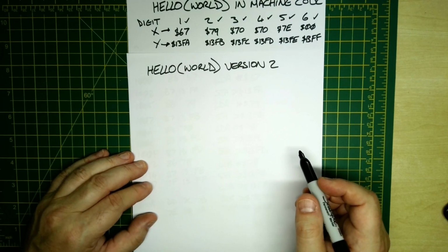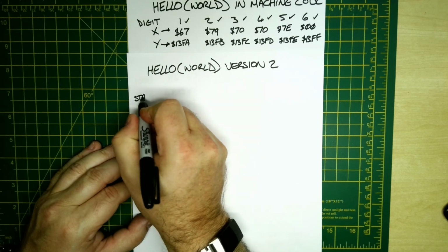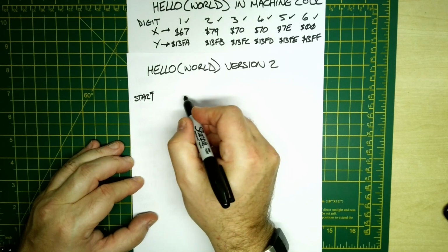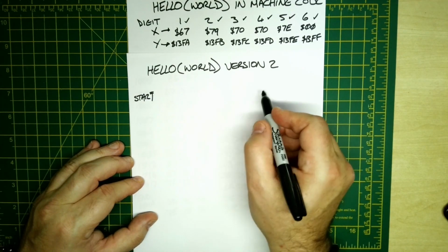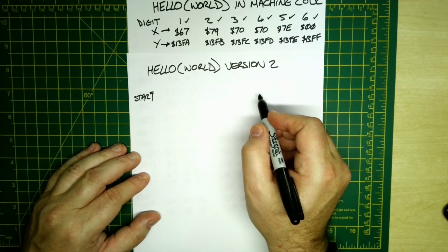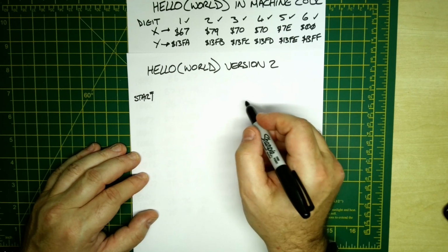So what we have to do first of all then, and let's just put a label at the top here. So I just put start. So this is where I'll put the labels down here. And then we'll have the address, then we'll have the byte code, the bytes, and then we'll put the mnemonics down the right-hand side here. So we're using the Motorola 6809 mnemonics here.